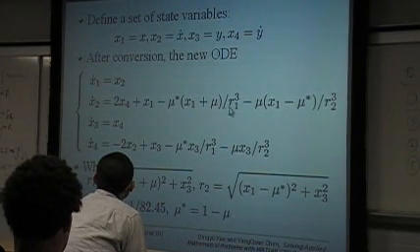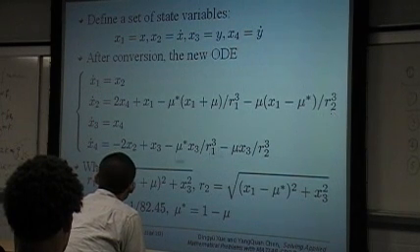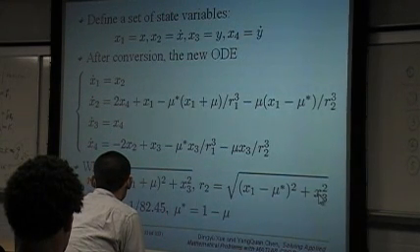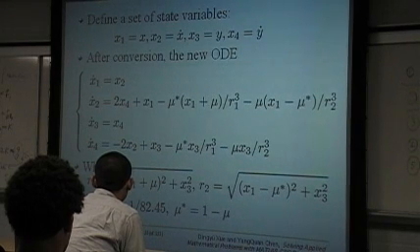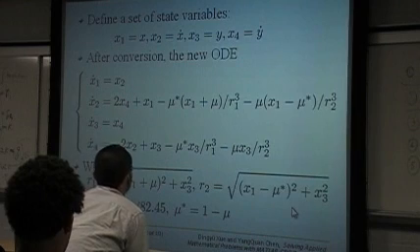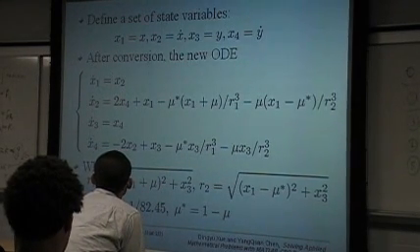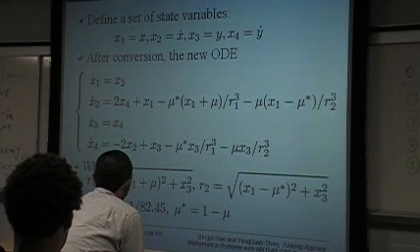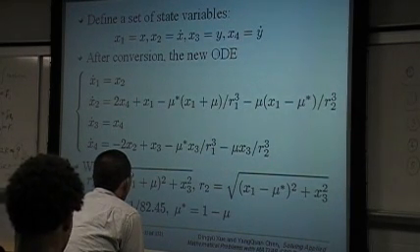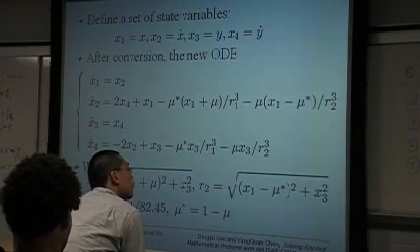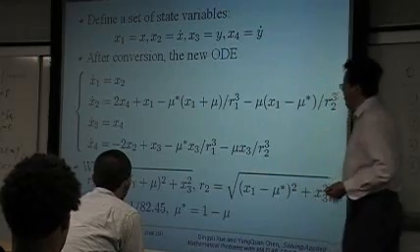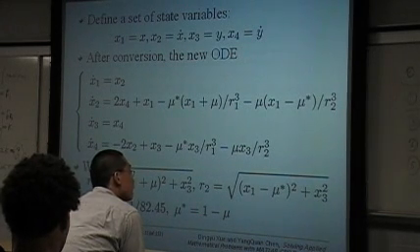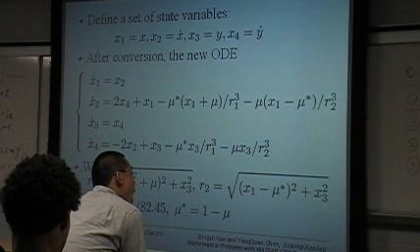And here we have variables r1 and r2. r1 is a function of x1 and x3, and r2 is also a function of these two variables. So to calculate the left-hand side of the equation, we have to calculate r1 and r2 first. Then we can use this formula to calculate the left-hand side of the equation. So in this case, we cannot use the anonymous form because there are intermediate calculations required. We have to calculate r1, r2 first, and then we can calculate the left-hand side. So we cannot use this form. The only way is to use the .m file.